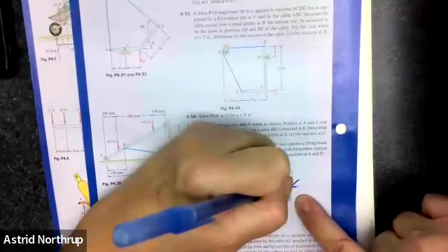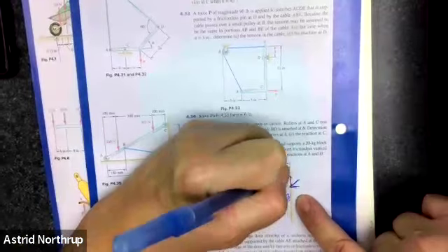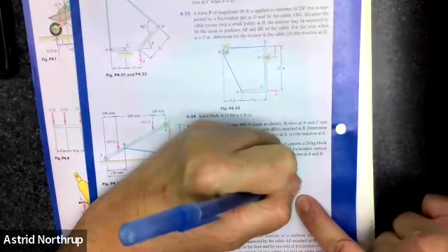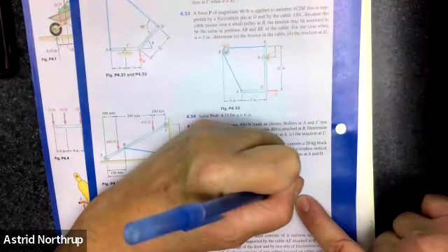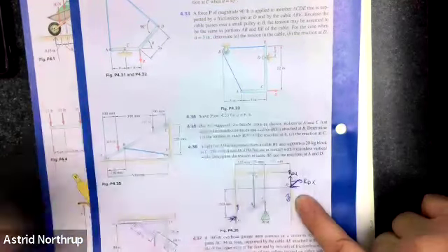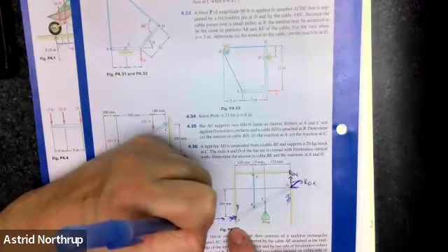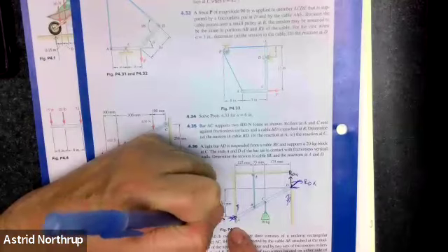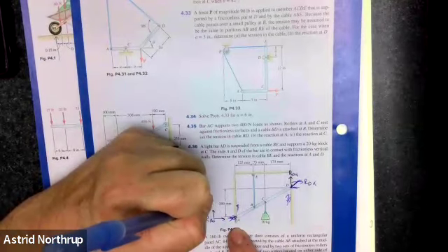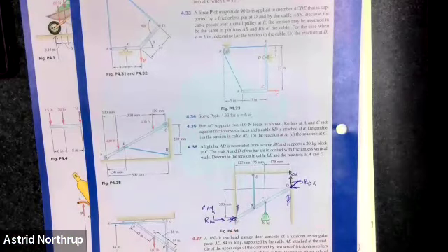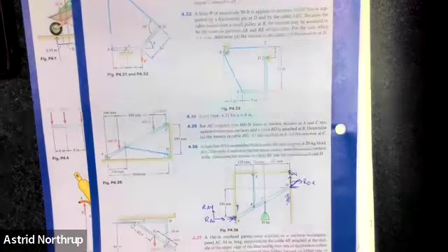You could break that into an angle, but my advice would be to resolve that into the reaction at D in the Y direction. I know it's pushing that way, but I'm just going to call it positive. And then the same thing here: reaction at A in the X direction, and reaction at A in the Y direction. Isn't it a frictionless wall? Oh, is it frictionless?